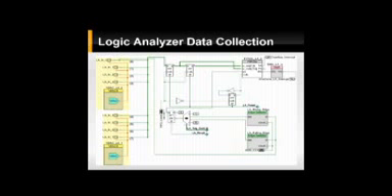The VDAC function is similar to that of the oscilloscope, providing a voltage which must be overcome to register a high digital level. The incoming logic signals then enter flip-flops, which store the current state, which is either high or low, on the rising edge of the clock input. Once 2 sets of data are stored in the top 2 flip-flops, a clock pulse is sent to the FIFO, which stores the bytes. Once 4 bytes are collected, a pulse is sent to the DRQ terminal of the DMA, similar to the oscilloscope, which transfers the bytes directly to memory. Upon filling the memory buffer, an interrupt tells the PSOC to transfer the buffered data to the computer through USB.